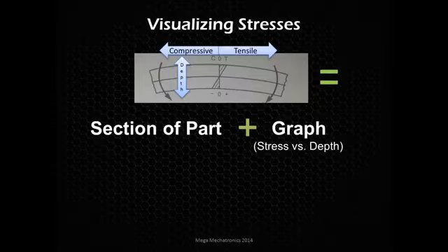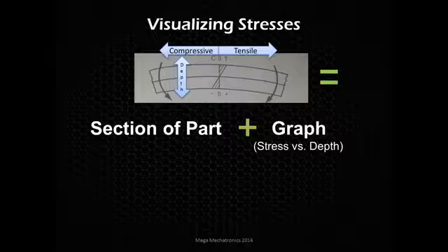So if we analyze this graph, what you're looking at on the top side is a tensile stress. And since that line is on an angle, that shade, it's crosshatched, you can see the maximum tensile stress that this part is seeing happens to be at the very surface of the part. And then we move into the middle, and you see there's no stresses there.